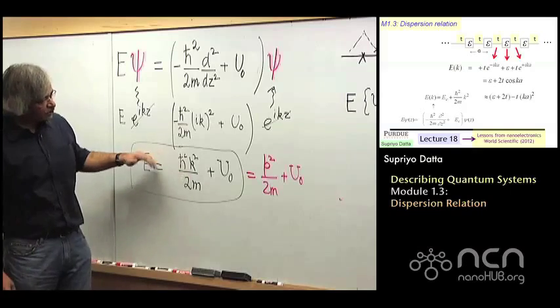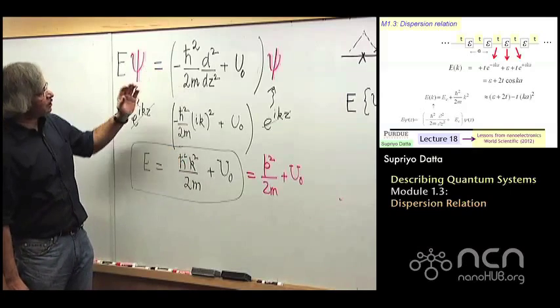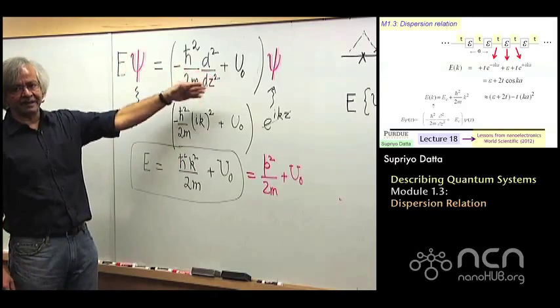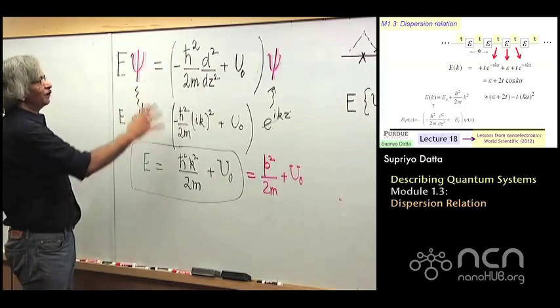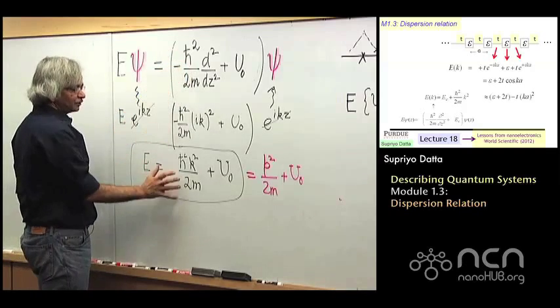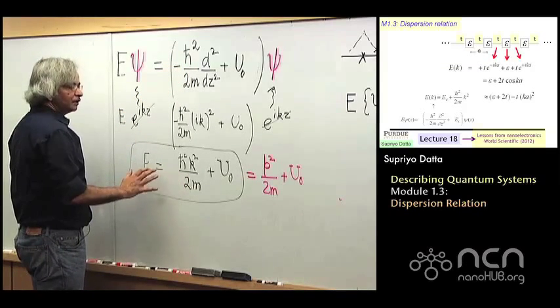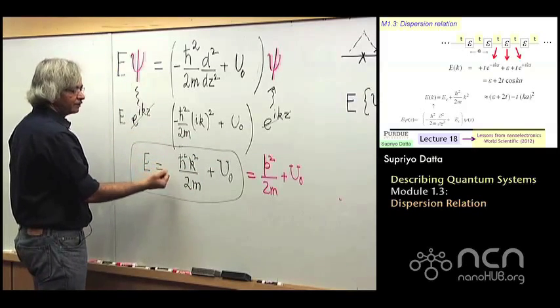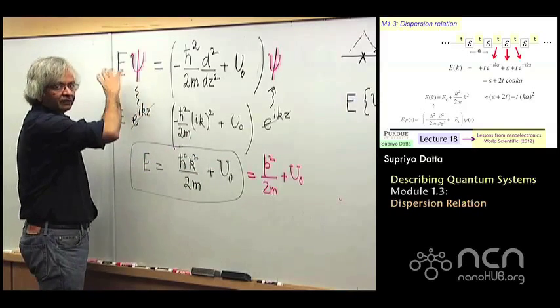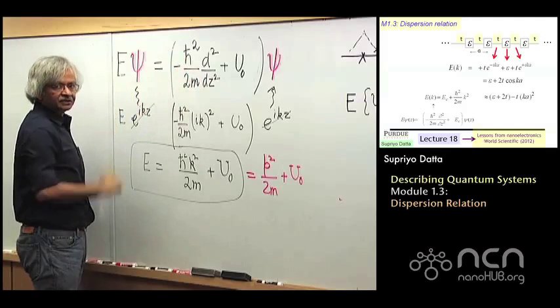And once you know this, you could work backwards and figure out the kind of effective mass equation that would actually give you that. So given an equation, you can get to the dispersion relation, or if you know this from various measurements, then from here you could work backwards and write down a differential equation that does this.